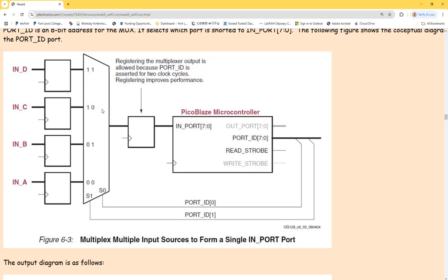Anyway. So there will be 256 entries, and it's selecting 1 of them, picking it up and sending it to the import. So the import is the core. That's the CPU, okay? And the CPU has 8 bits to receive the 8-bit data from one of the ports. So my question is, why did the designer design 256 ports? And definitely the modern CPUs probably have a lot more, like 2 to the 64 or something. I don't know. However, why is this beneficial?